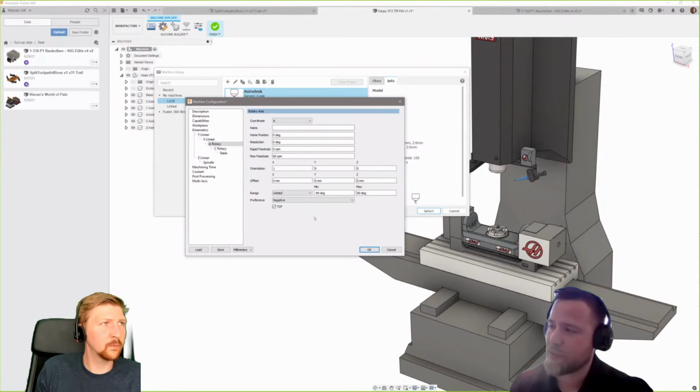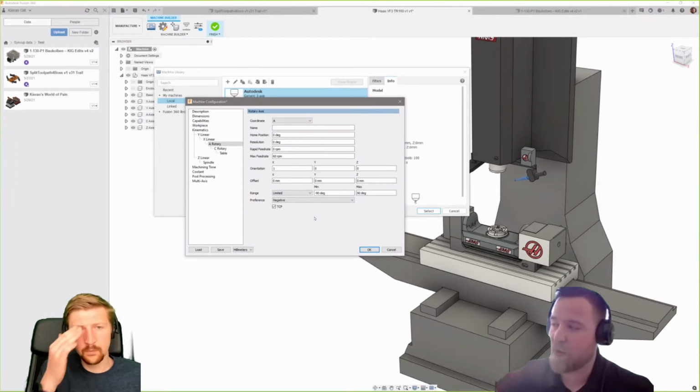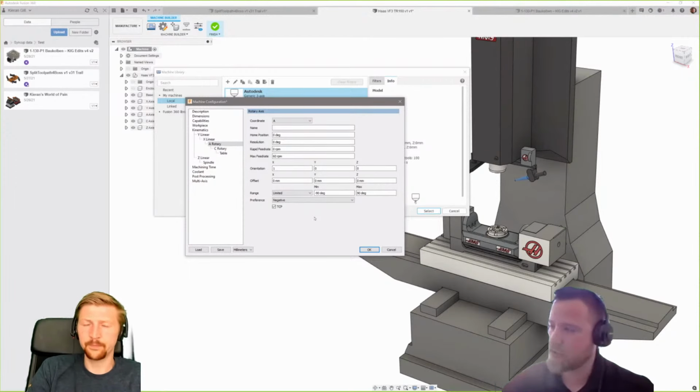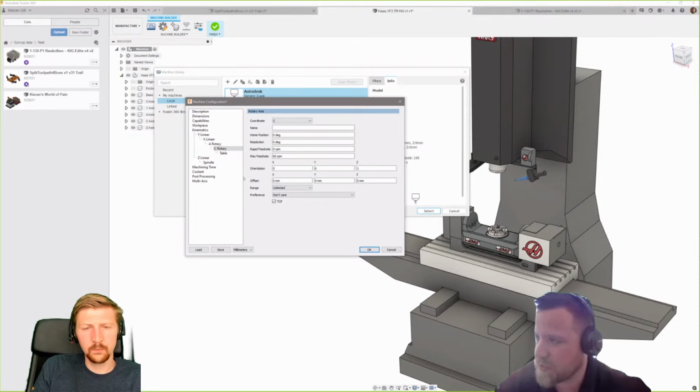I want the machine to actually swivel its A-axis minus 90 towards the back of the base so I can see what's going on in the machine, rather than the trunnion actually flipping towards me so I can't see what's going on. So hence I'm choosing a preference one over the other. So that's really important. And then on the C-axis, actually, it's unlimited and spins through 360 degrees, so I don't need to do anything there.